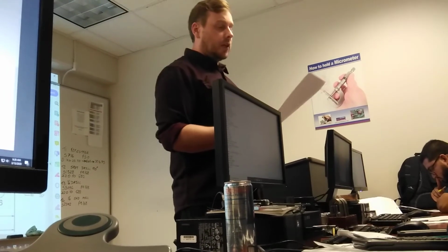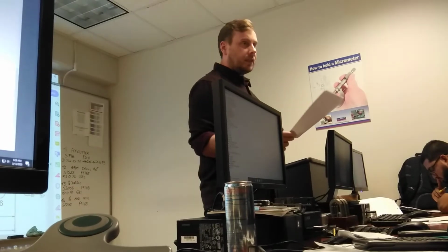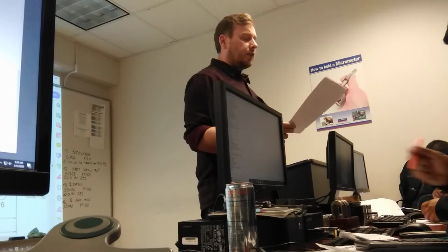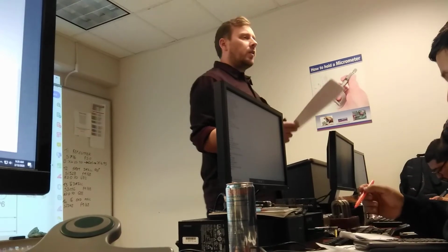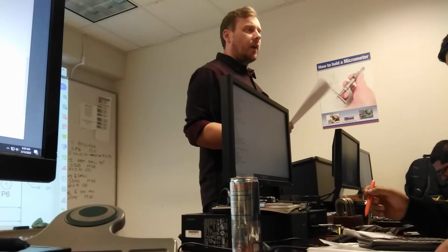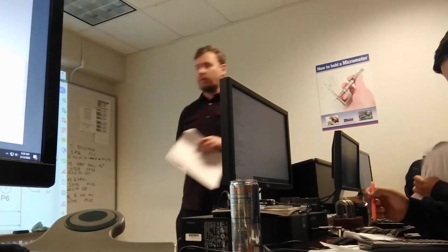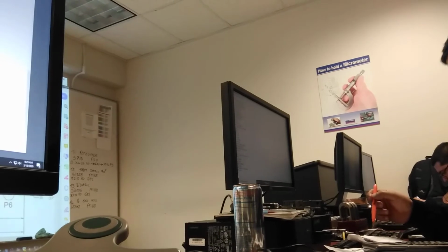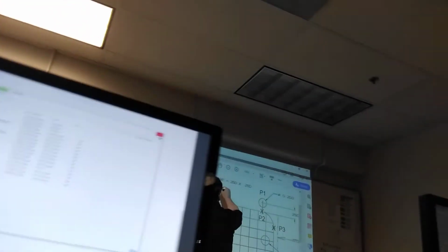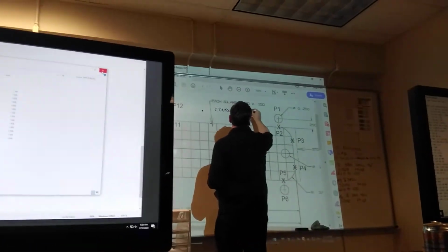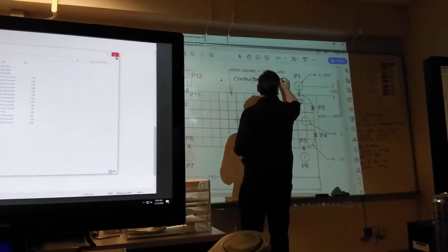So if the spindle is turning clockwise, as it usually does, highlight this: cut a contour, cut the profile or the outside, in a clockwise direction. Contour, some people might call it a profile, or the outside of a part.